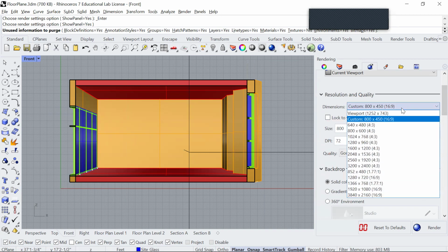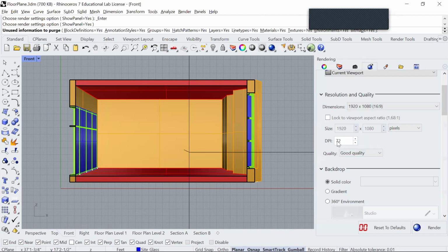When you set the rendering settings, we talked about this in the previous panel. So we want to make sure we have a decent dimension for the rendering. The higher the better, but the more time, so you can go to the 3000s and so on. Again, these are small drawings, so you don't want to pop up the resolution of the rendering too much, but not too little. So you might want to stay in the 2000s and keep this no more than 300, good quality.